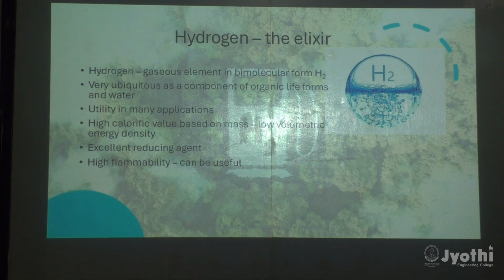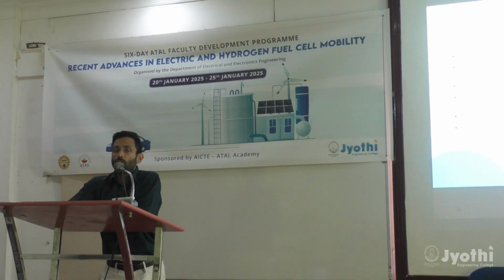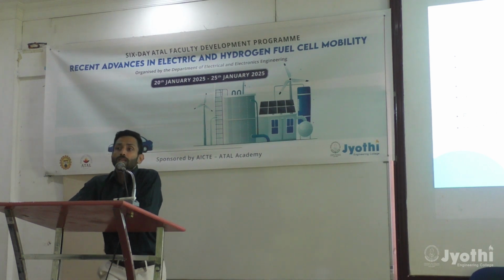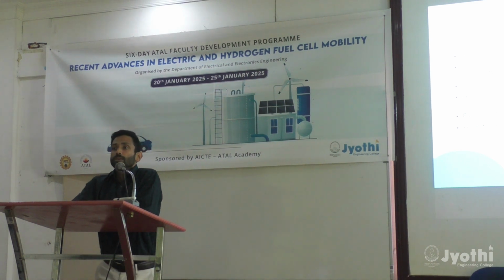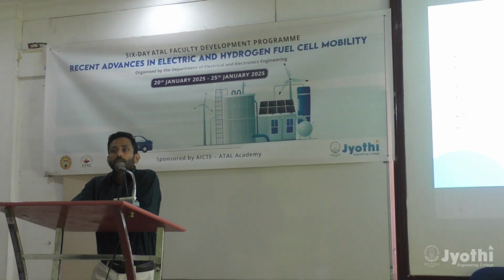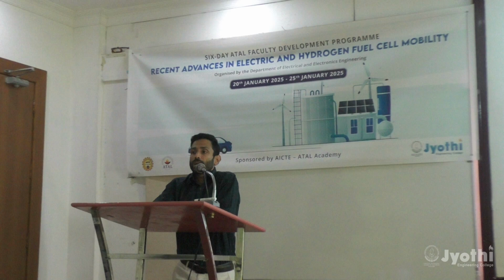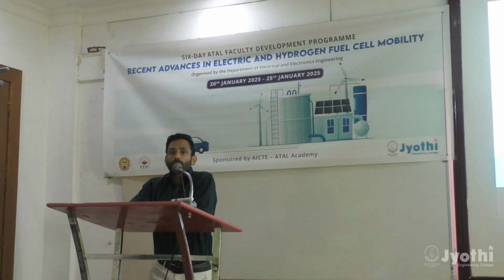The important thing to note here is that hydrogen has a very high calorific value, but it has a very low volumetric energy density, because it is a very low density gas. If you want to increase its volumetric energy density, then you will have to increase the density also, meaning you will have to compress it to a very high pressure in order for the density to increase.